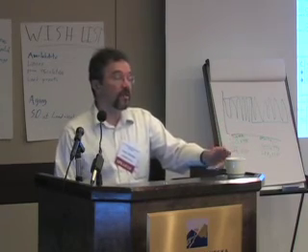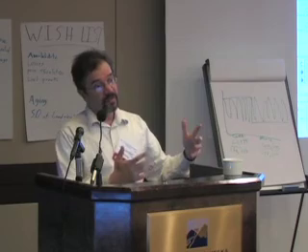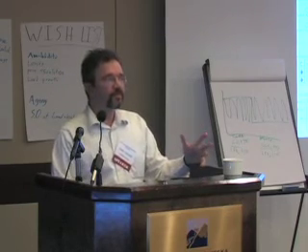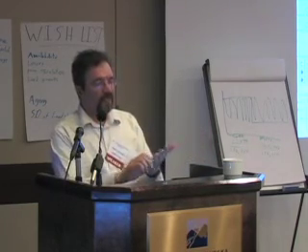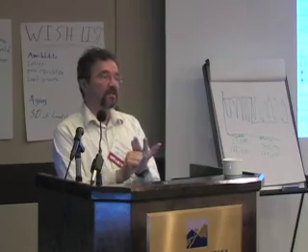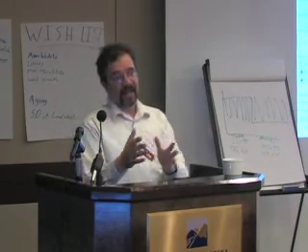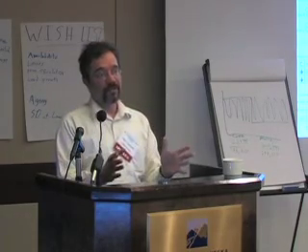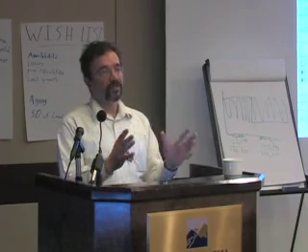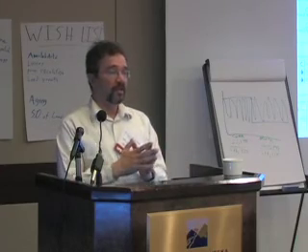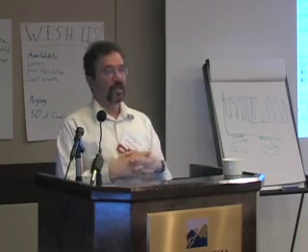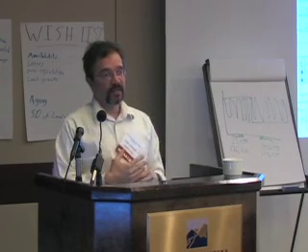We haven't done as good a job as we should of pulling those together, and the individual components are easy: the PV production is accurate. The wind turbine production is as accurate as the power curve that you use. So there's this whole controversy with small wind turbines about whether the manufacturers are exaggerating their power curves or not.